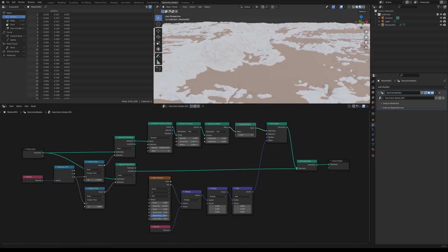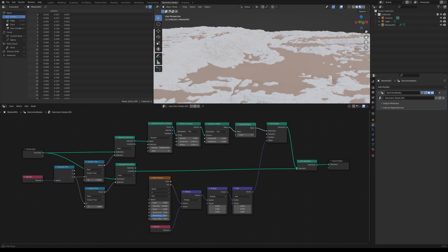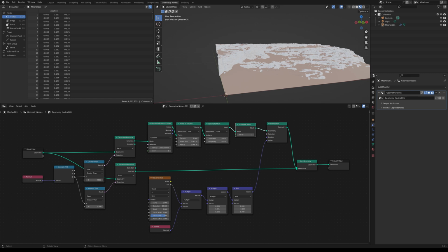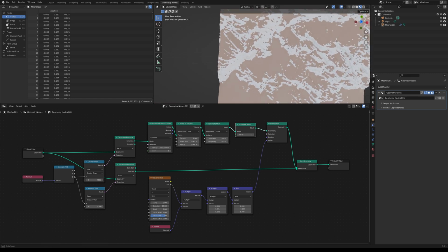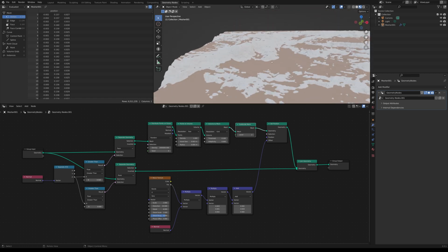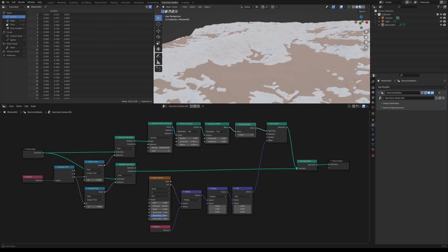And there's a lot of ways, again, you can do this, but I think one of the easiest things we could do is just reproject our texture back onto this new terrain using a projection method in Blender, and that will just create us some new UVs. And UVs for height mapped geometry is really straightforward because it's really just like a planar projection, a top-down projection for the UVs. So it's not hard to get back if we lose them.